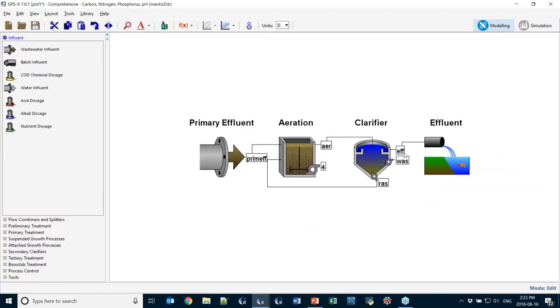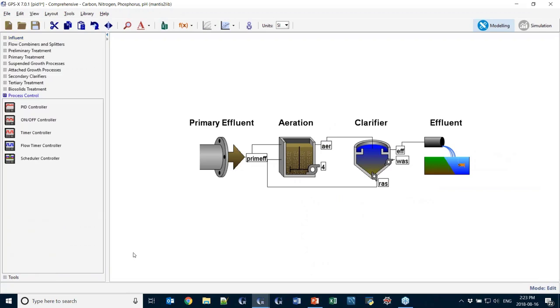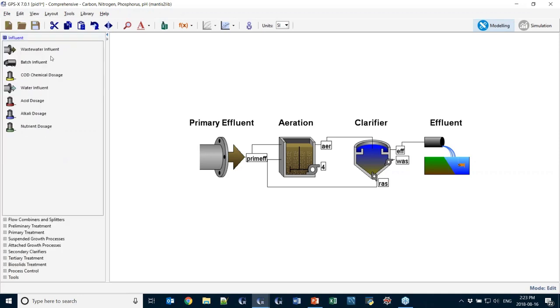As I mentioned, that was built into here where you saw that unit, so that's already there. If, as I mentioned before, you want to set up a PID control loop, but you don't have that controller already present on the menu for a particular parameter that you want, you can actually grab this PID controller here and just drop one of these on the board and then install both the manipulated variable and the control variable and just do all that tuning and everything just like we did now. And those are sort of free-form ones that you can add as required. Okay, back to the slides.